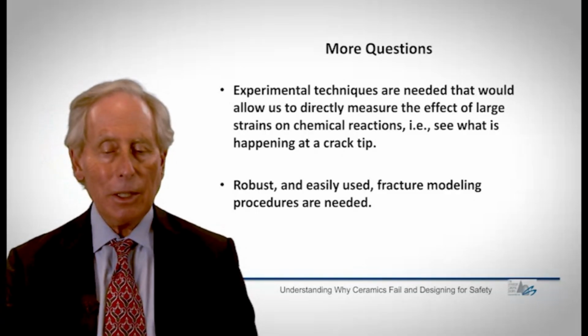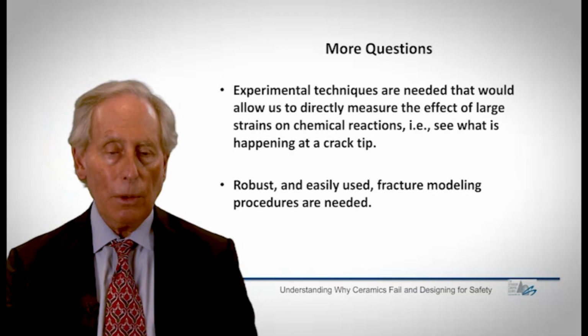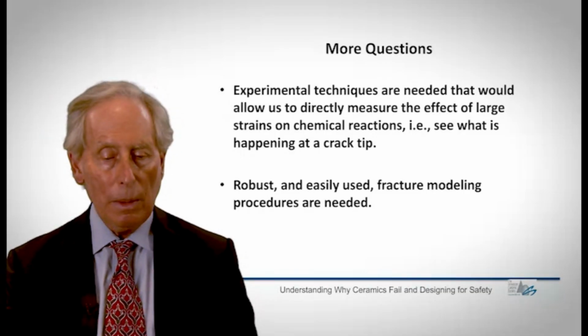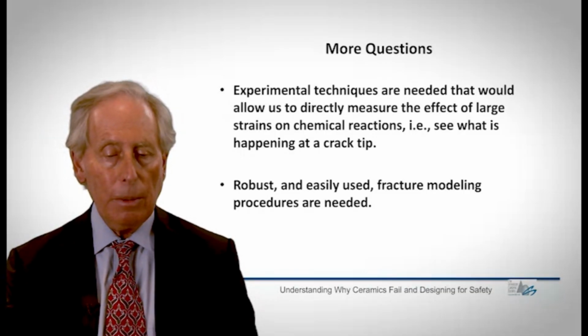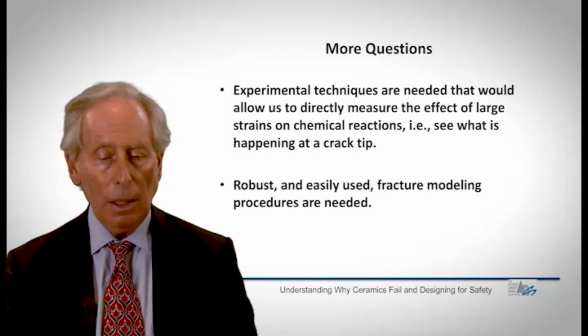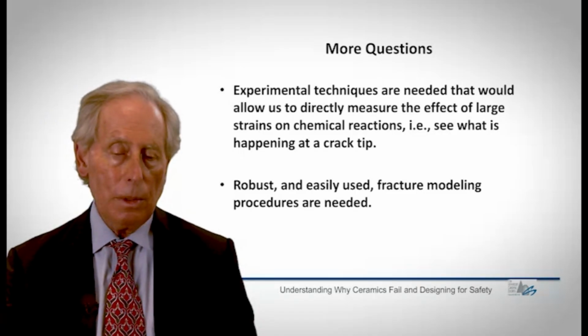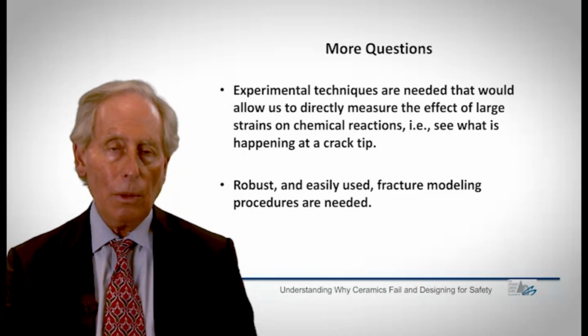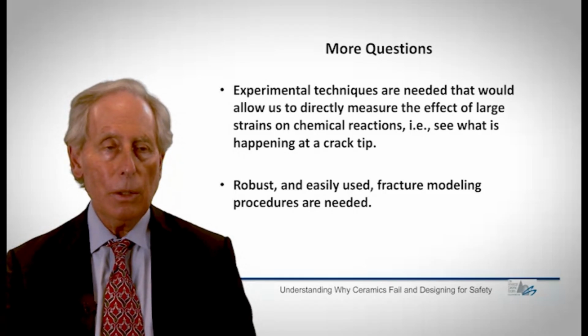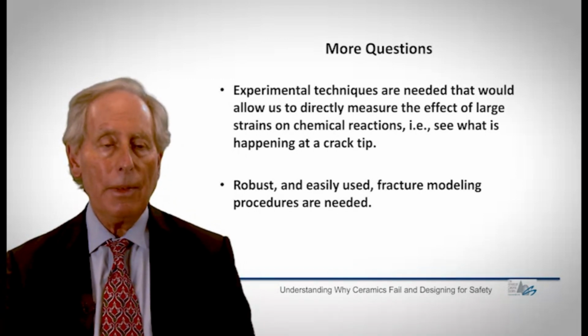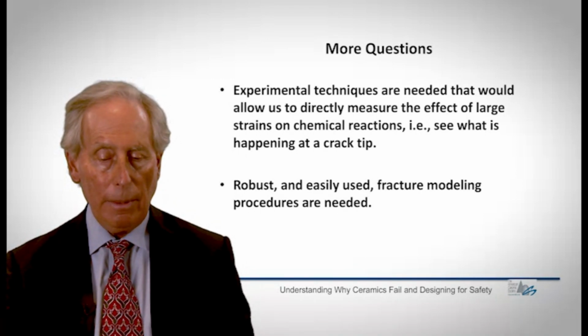Again, what mathematical expression should I use to fit our crack growth data? I showed you two different ones, one being an exponential chemical rate theory, which appears to be more fundamental, but the stress dependence in that expression is somewhat arbitrary. And whether my empirical crack growth law is sufficiently robust to use to predict failure times is still open to question, but it's available to us, and I think it's a better solution than anything else we have at present.